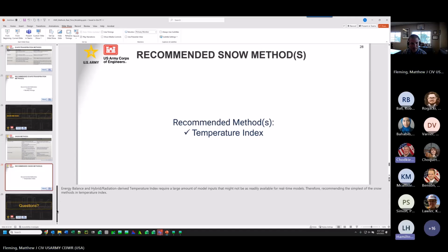Kevin, one thing that we've noticed in our basins is that for snow, we have to use different zones to calibrate. We need like the high elevation and the low elevation, basically. So if you're setting that up, I would recommend that. Yeah, that's a really good point, Leah. Your zone configuration for snow is going to look different than the other configurations because snow parameters are more regional, I think, right?